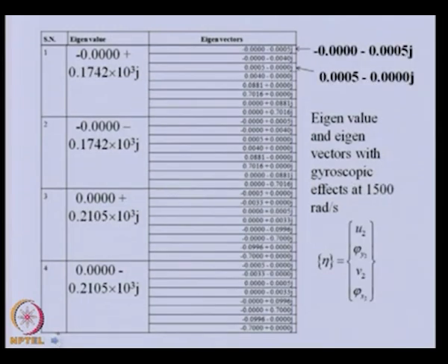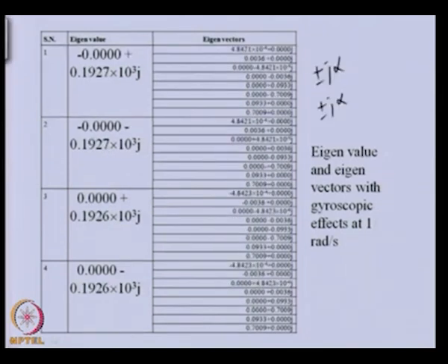So this is for high speed. So for high speed, we expect that now this eigenvalue, so this is one complex conjugate. This is another. So now they have different values, and you can see one is less as compared to the previous one, and another is more. So basically the splitting of the natural frequency is taking place. So we can see that it was 1927.